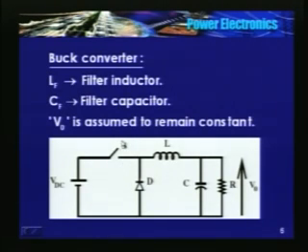What sort of a switch? Can I use an SCR in this circuit? My question is, can I use an SCR as the switch in this circuit? The answer is both yes and no. Why yes? In principle you can use it. It is a controlled switch, I will apply a gate signal, it will turn on and I have to turn it off using some other means.